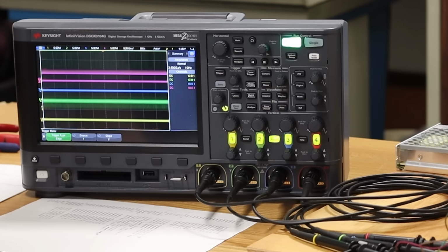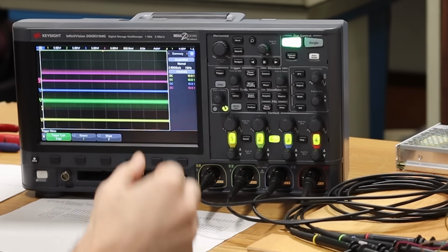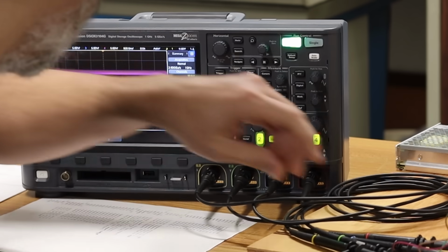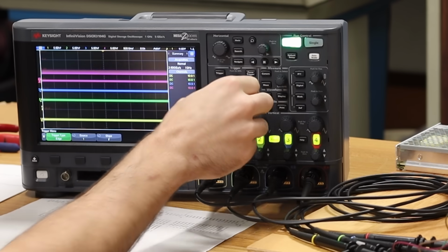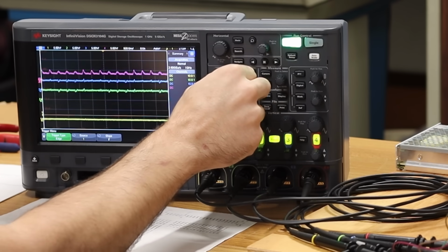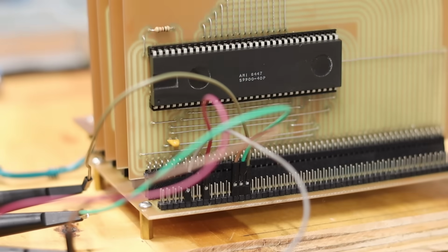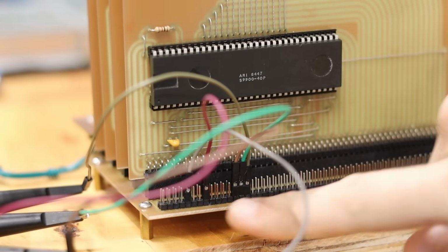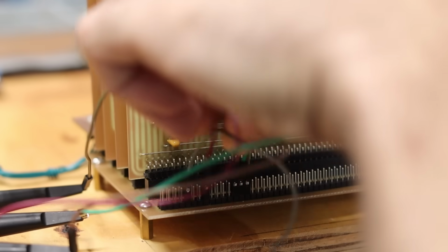Boy, that's wildly different looking than I was expecting. It looks like I've got some settings wrong here. Let's see here. There we go, 10x. Okay. It doesn't look like our clock is going on. We should be triggering off of the clock here, and it doesn't seem like we are. Right, I forgot about this. This is a problem from last time. The clock doesn't extend to this front header that I've got all this stuff plugged into. Everything else does, but the clock doesn't, because I don't know.